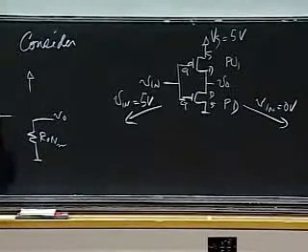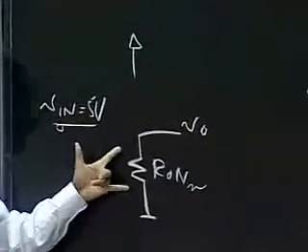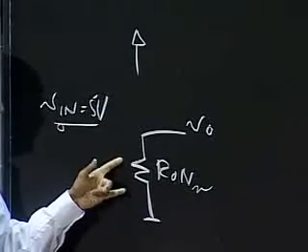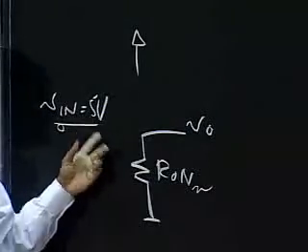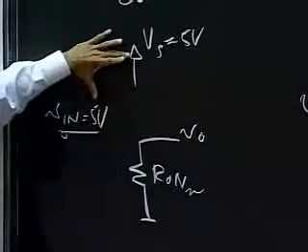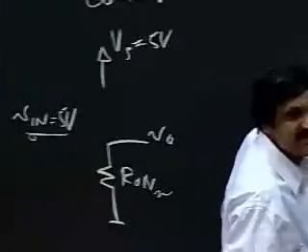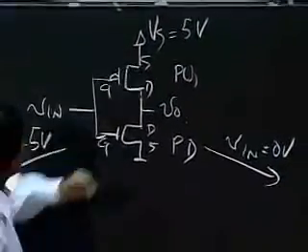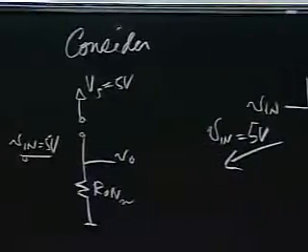When Vin is 5 volts, the N-channel MOSFET below is turned on, and so I have an R-on resistance here. But remember, if Vin is 5 and Vs is 5 volts, then the voltage across the source and the gate of this P-channel FET is now equal, 5 and 5. Okay? So this one will turn off.